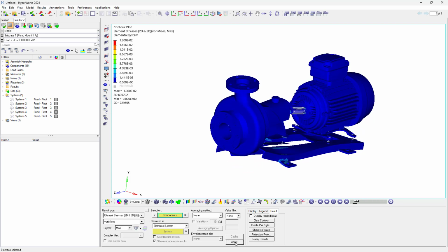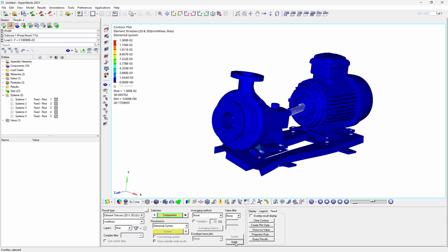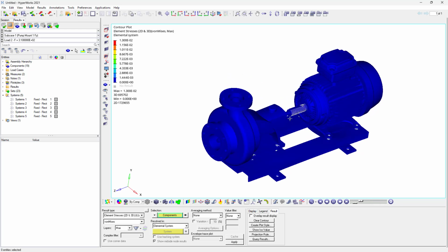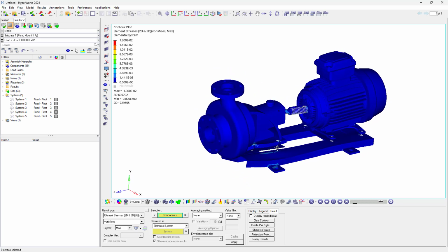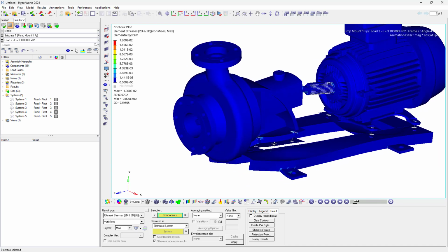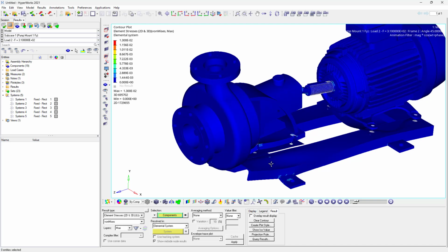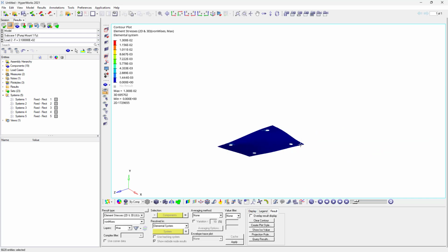Yeah, you can switch to elastic strain energy, elemental strain energy, sorry, and then we have the stress plots. So now it is globally taking the whole model. What you can do here is simply isolate the plates. Just pause the animation. So these are the options here. It's the isolate option, and if I isolate this one, only a single plate will be isolated.